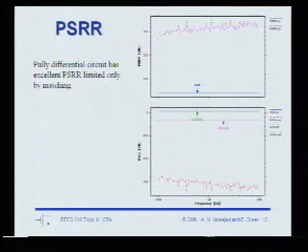Here's also a plot of the gain. So it's kind of hard to read, but these are the various gains in the circuit. You can see, for instance, this is again the gain from VDD and VSS to the differential output for the fully differential circuit. And really that's captured by this ratio here. Okay?